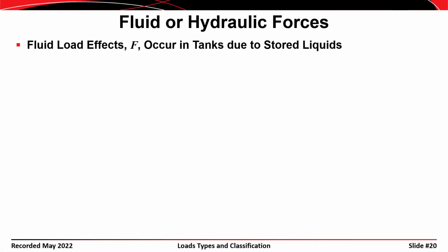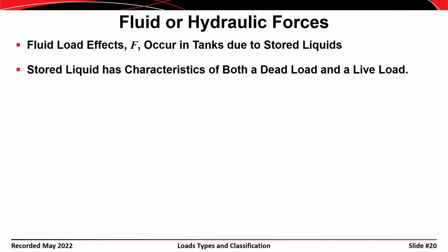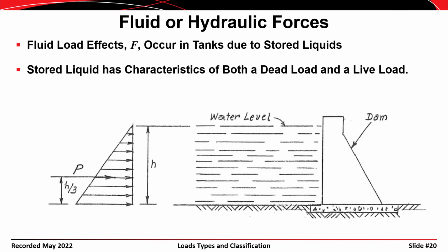Okay, fluid effects occur in tanks or other cases due to stored liquids. Stored liquids have characteristics of both a dead load and a live load, so they kind of bridge the gap between permanent and transient. One of the common cases that we as civil engineers would run up against is structures that retain water, like dams and weirs. You certainly could be called as a structural engineer, though, to consider things like storage tanks and water tanks for water distribution networks and things of that nature. I have a good friend in Italy who does a lot of work on seismic performance of storage tanks.